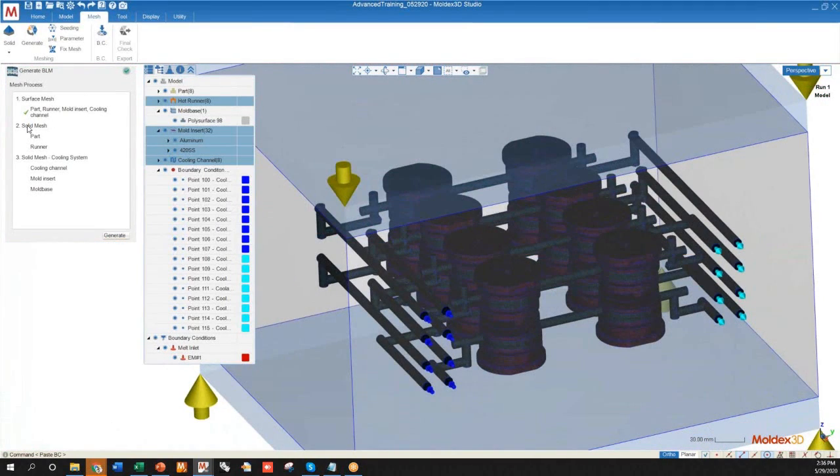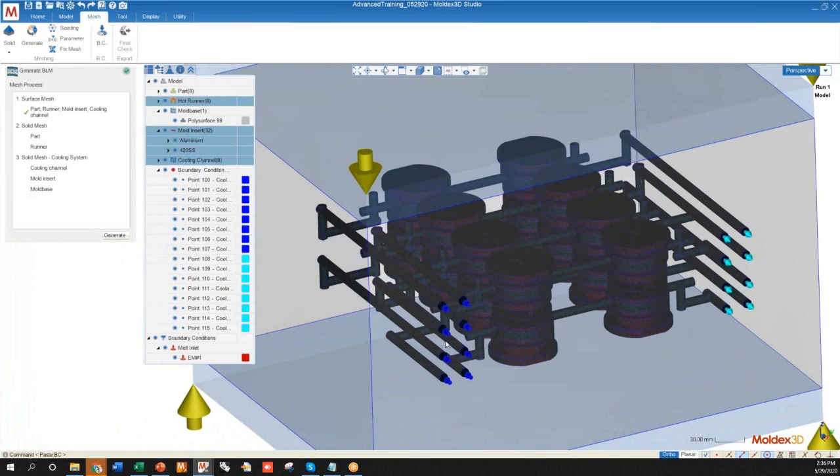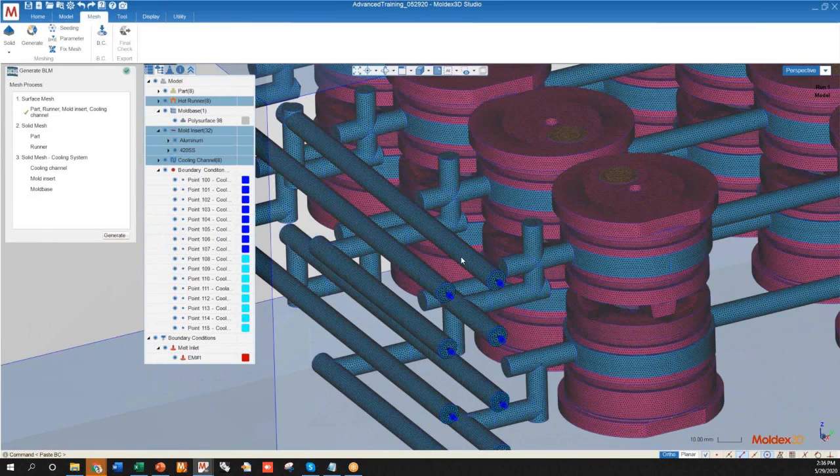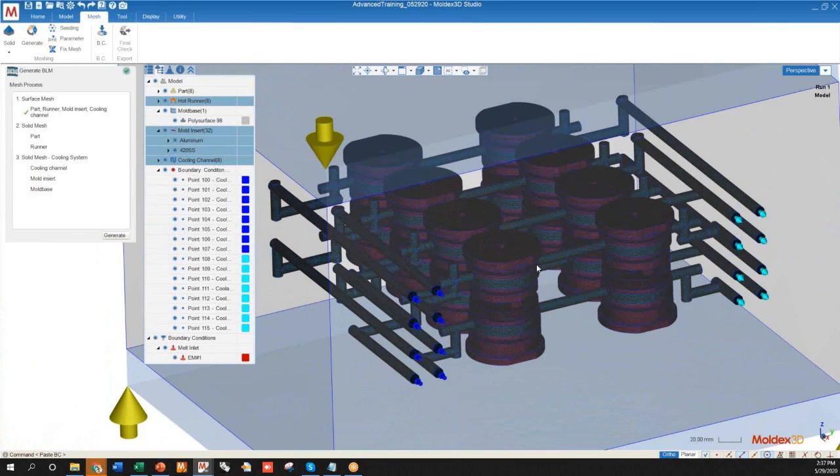Like I said, from the surface mesh, it's quite straightforward to generate the rest of the solid mesh. The surface mesh is really the tricky part. And as long as you go through the process like I went through here, you can see that even for a pretty complex system, I would call this relatively complex, we actually get a perfect surface mesh right out of the gate. And if you follow these practices, probably anywhere between 70 to 90% of the time, you shouldn't have any issues.